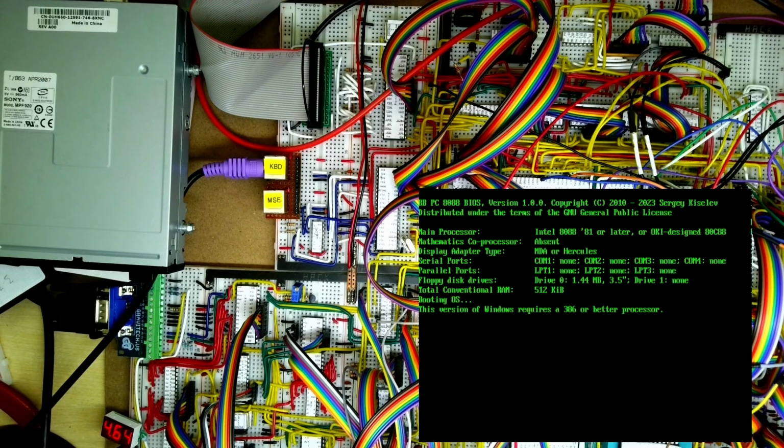So what it does indicate is that all the versions of MS-DOS I wasn't previously able to load, I am now able to load. I will try and add some more files to those to make the disk a bit more interesting, but it's achieved the purpose of using programmed I/O. This actually seems to have got it working more reliably. I did try all these floppy disks in the BIOS with the DMA enabled, and it still wasn't reliably loading a lot of later versions, so there is still a problem with DMA on the board. But the fact that I've got the PIO, programmed I/O mode working is good.